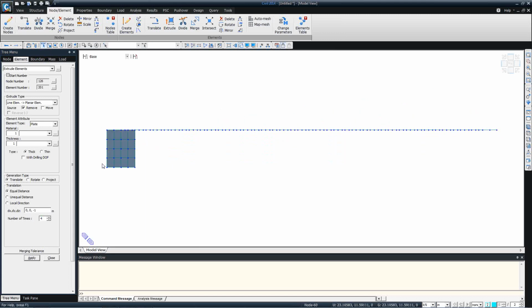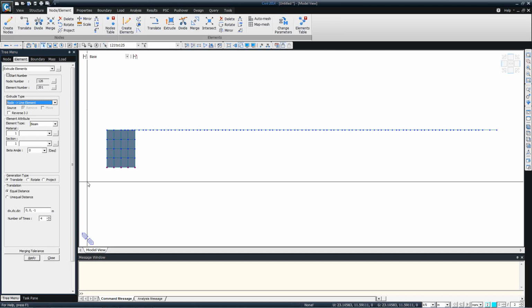Simply copying here and changing this to node to line, and say normally we have the soil profile for the pile at every 1 meter interval. So we know how the subgrade reaction changes at 1 meter intervals from the soil data, because soil structure interaction is very important for integral bridges. We therefore have to consider a good amount of accuracy when assigning the soil springs.